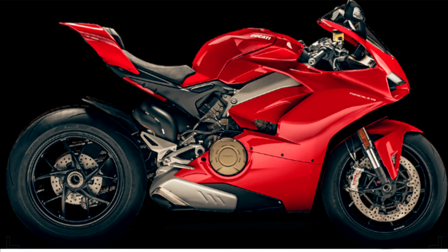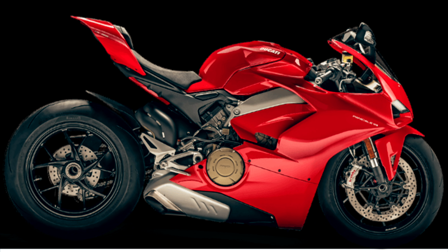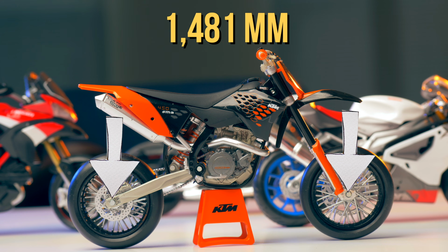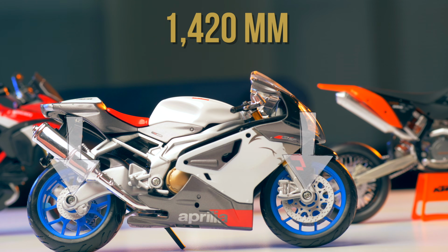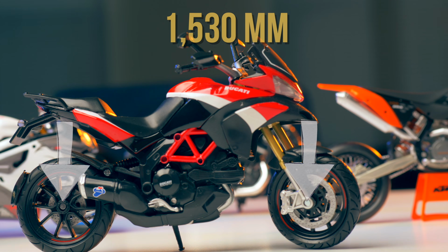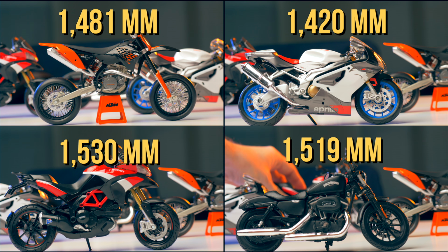Okay, cool, let's add some rake to our motorcycle, and also some brakes. I mean, it would be good to be able to brake before the corners, right? Now, what will happen if we apply the front brake with our front fork at an angle like this? Well, first of all, the front forks will compress. This causes the wheelbase to decrease, simply because the forks are moving at an angle. So the wheelbase is the distance between the front and rear axles. A bike with a short wheelbase will transition side to side and turn quickly, but has the downside of being unstable. A bike with a long wheelbase will transition slowly but will be more stable.